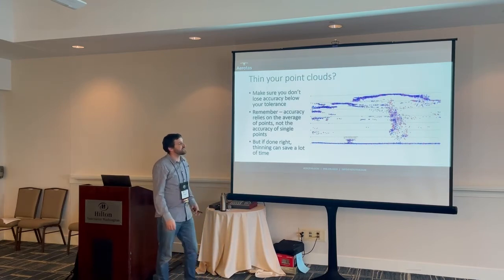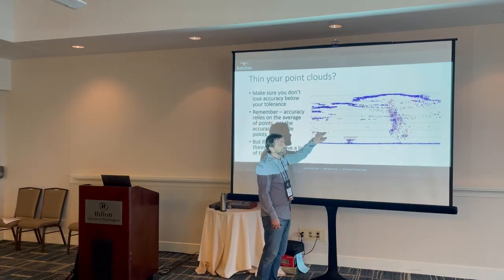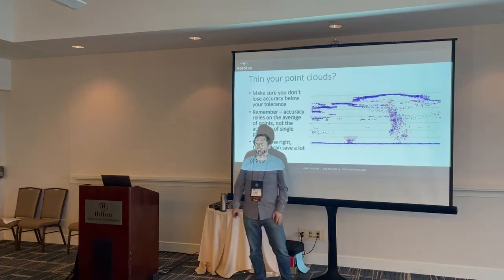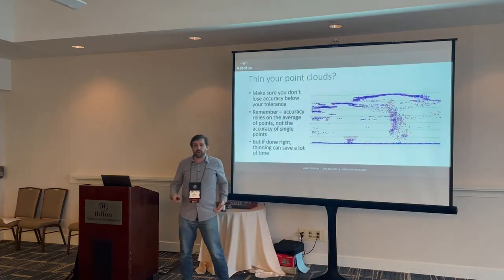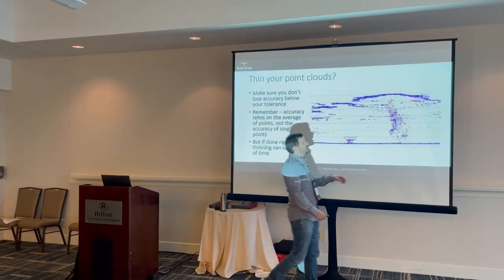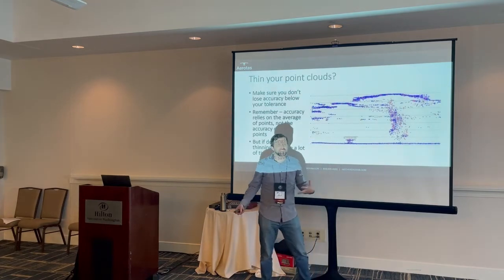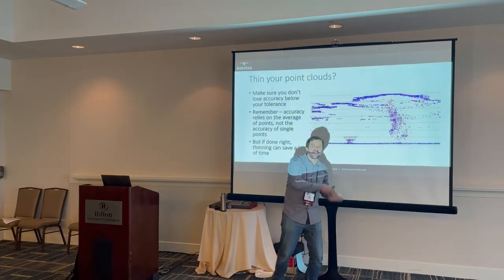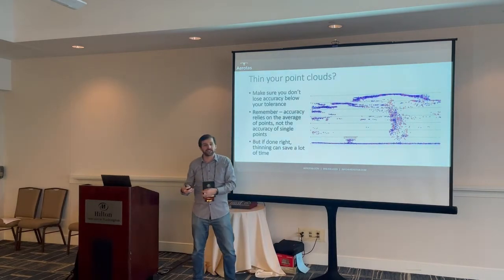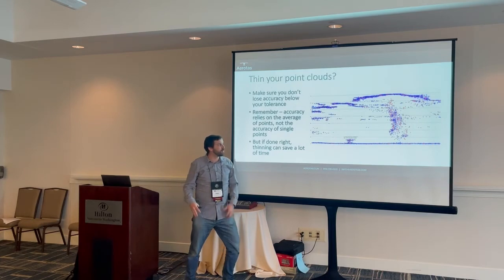There are 3D thinning algorithms where if you have a point that's pretty much by itself, it'll keep it, and if you have points that are in clusters, it'll combine those into one point. Well, that's actually a really clever way to do it, but it's not a statistically average distribution, and you might have way more density in a trunk. Especially when you're dealing with grasses, it might make grasses look more like asphalt, because it's combining all of those into the same density of points as actual asphalt. So it's not great when you're dealing with partial vegetation.